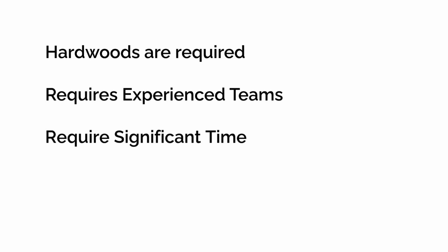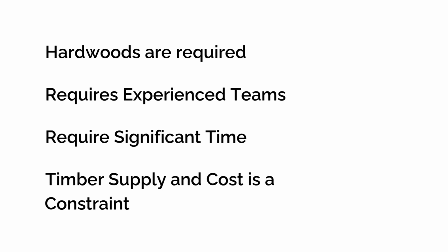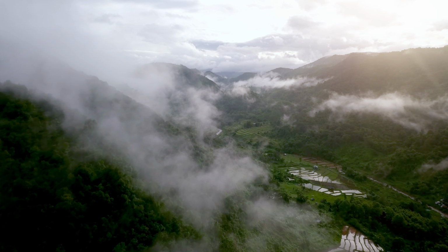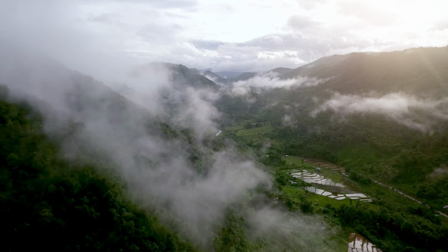You need hardwoods like Ekki or Greenheart. The work's got to be undertaken by experienced teams. The possession time planning is difficult due to those long installation times, and then timber availability and cost can also be a constraint. Also, let's not forget, sourcing tropical hardwoods does carry a big environmental impact, something to consider.